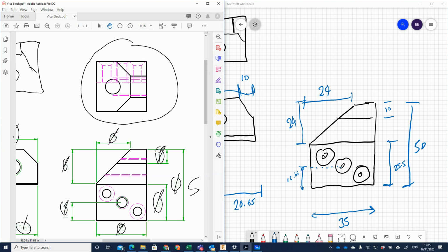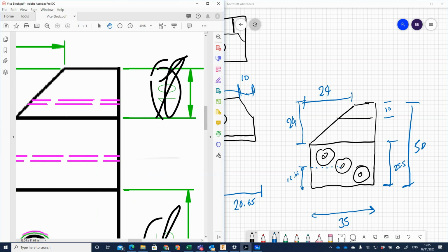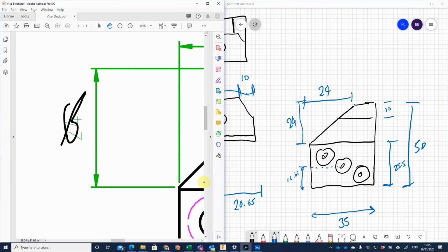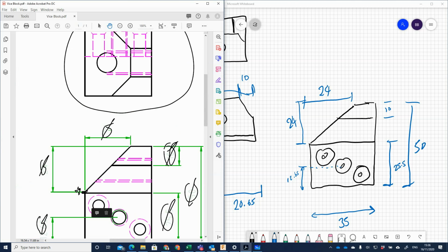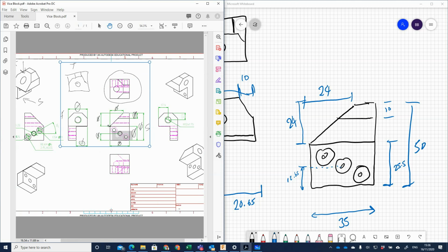We have to be careful in this drawing: when you zoom in, it's like this 24 here, and that line there is actually a 0.5 mil gap between the two. So 25 and then 24 obviously only make 49.9. Okay, so we've got those dimensions there.